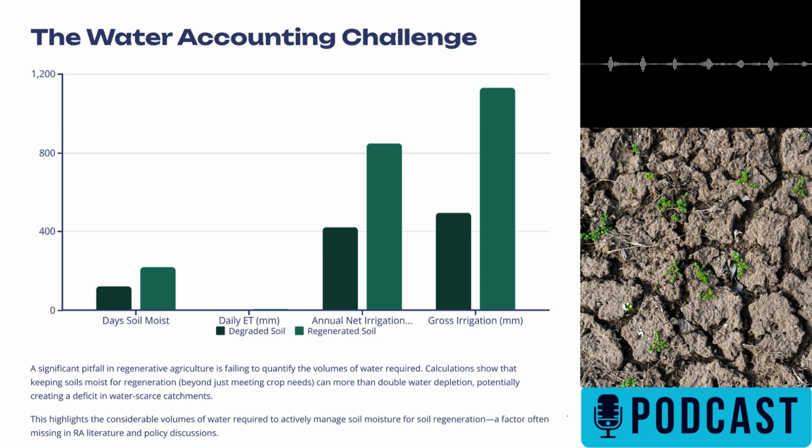Precisely. Now, RAM specifically relates to the water held in the medium-sized pores in the soil structure. Technically, it's water held between certain tension levels, usually -10 and maybe -100 or -200 kilopascal. Okay, getting a bit technical, but basically it's how tightly the soil grips the water. Exactly. RAM is the water held loosely enough for roots to easily slurp it up.